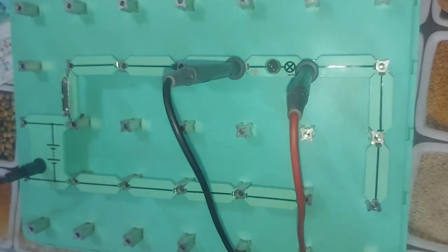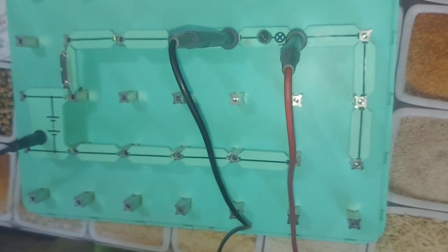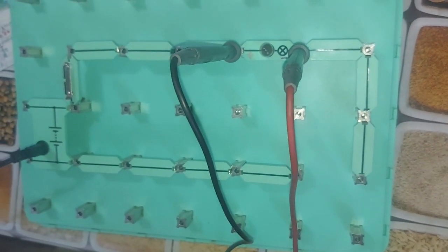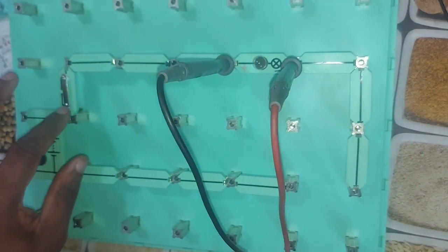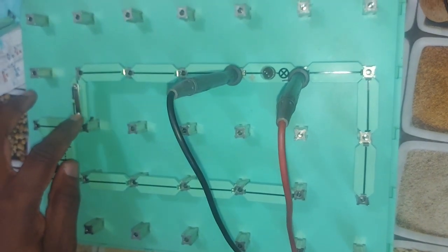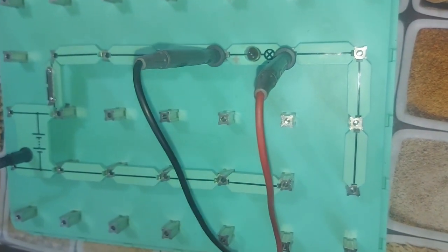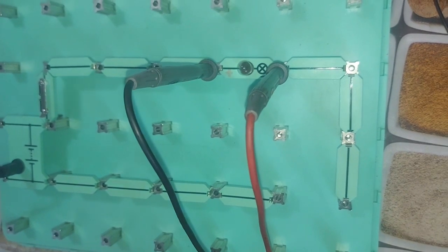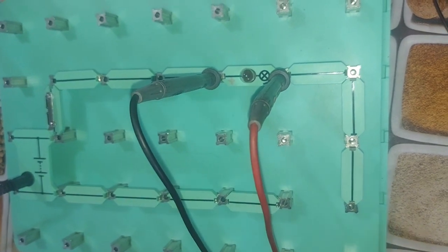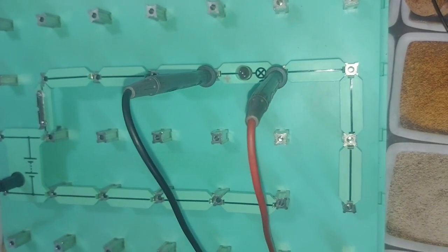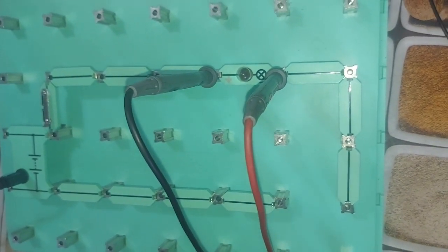So how do you know? I have told you for now that we have an open circuit, okay? How do you know we have an open circuit? One thing that can easily help you is when you flick the switch and you find that your load is not working. Okay, definitely, this might not be an open; it might be high resistance or a short, which might do the same as well, but you have to start somewhere. So let's say, right, let me investigate if this is a short or if this is an open. So now we want to start with an open.